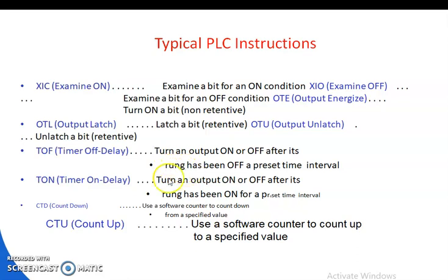TON, turn on delay timer: the turn on delay timer turns on after its rung has been on for a preset time interval. CTD, count down: the use of a software counter to count down from a specified value.